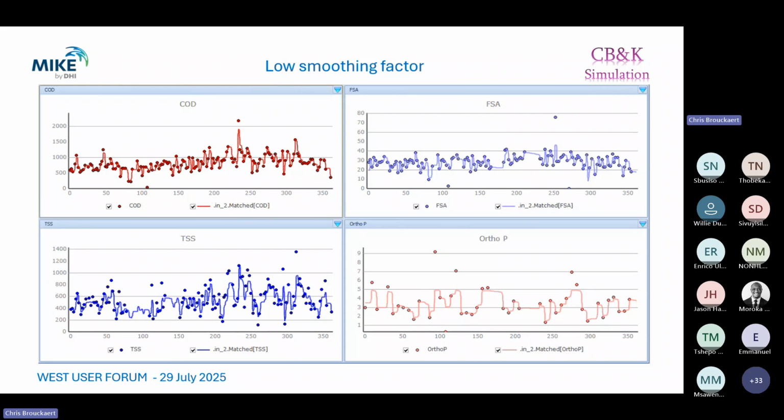And with a low smoothing factor, the optimum composition tracks the optimum point more closely, and it jiggles around with it. So you can see that it's really jumpy. If you look at this point, it's really following what is probably a wrong measurement, and so on.